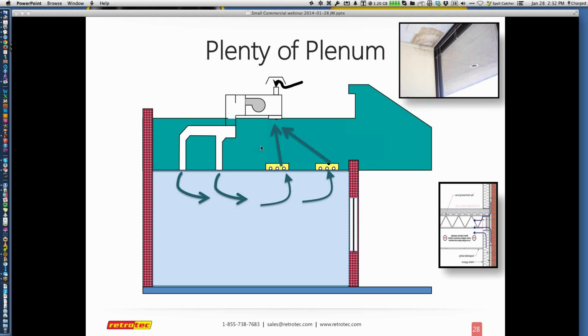The illustration that I have now refers to drop ceilings that are used as a plenum, and the plenum is where all the return air is brought back. You can think of this whole drop ceiling up in green as an area where all of the return air gets brought up on the other side of the drop ceiling, moves around anywhere, and finds its way back to the return path. It's conditioned and brought back into the structure with the white ducts here. So there's no actual return duct system in this illustration.